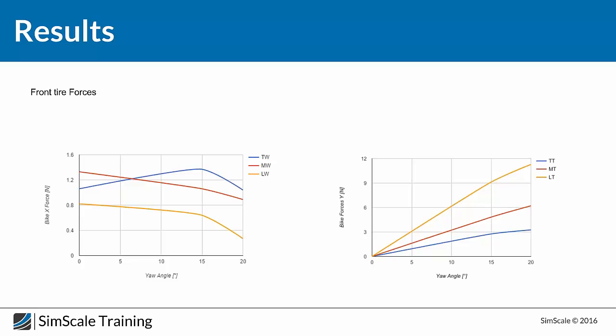But as we can see from the lateral or side force, of course the large tire creates significant side force because of the difference of pressure between the two sides, and also the geometry and the area of the tire. And that's, I think, Akram, very important to understand, as I would say a very familiar misconception in aerodynamics: drag is not because of the friction between the air and the surface, or not mainly, but because of the pressure difference before and behind the object.